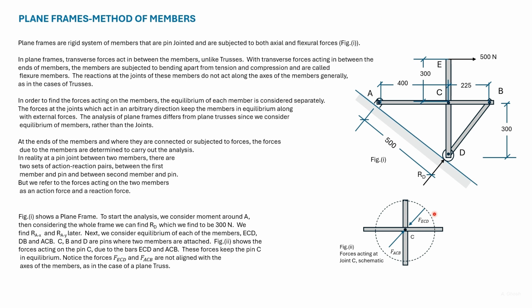These two forces act on the same body, which is the pin. Action-reaction forces in Newtonian terms act on different bodies. So these two forces are not action-reaction forces in Newtonian terms. These two forces are also not aligned with the axis of the members.